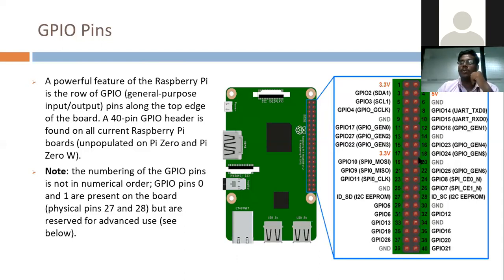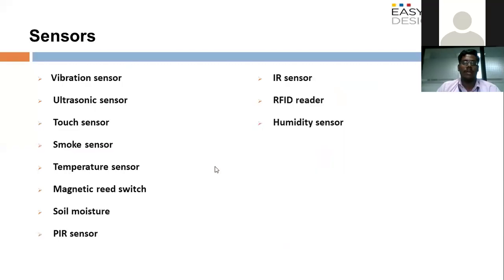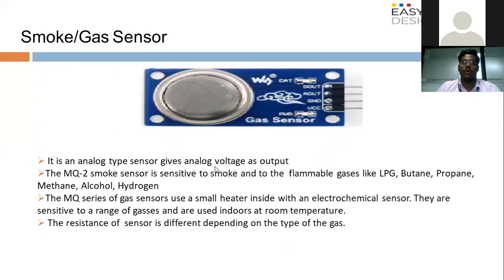So the 18th pin is the echo pin, and then for ground, whichever ground you need, you just plug it to a ground. I connected to the 30th pin. The 30th pin is a ground. So this is how we connected, and this is my code. I will show you how to type the data inside the file, and also how to run the code.